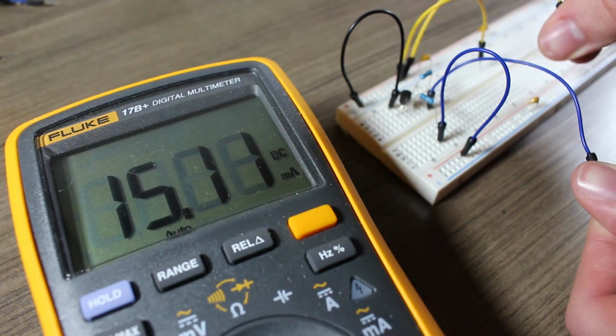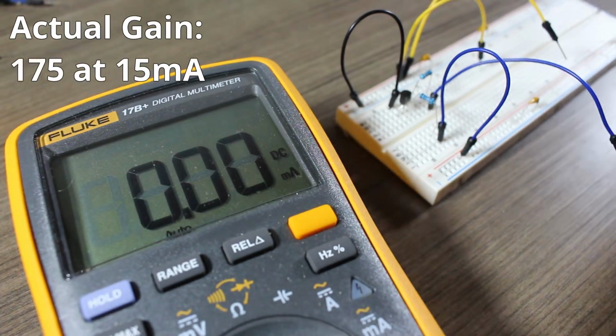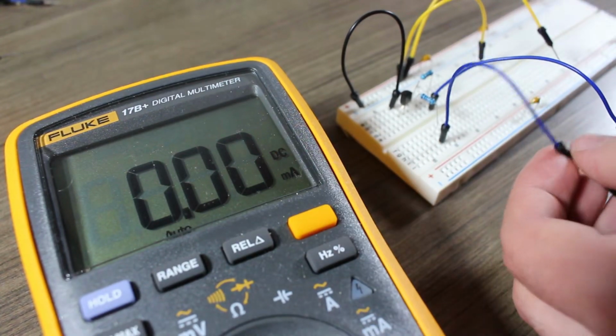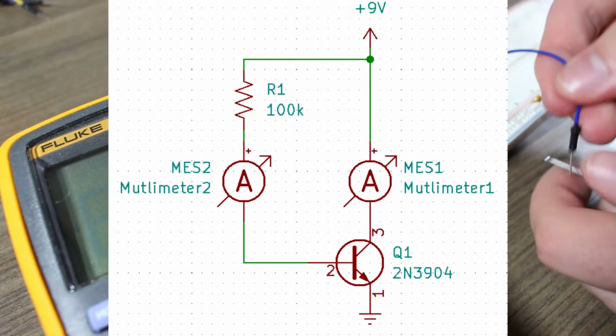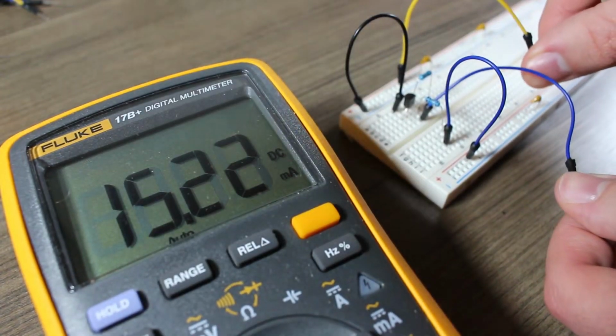If we solve for beta, we can see that this particular transistor has a gain of 175 at a collector current of 15 milliamps. This value is within the datasheet's range, so the math checks out. And for further proof that this transistor acts like a current source, I'll remove the resistor and connect the pins directly to the supply rails, and we will still measure that same 15 milliamps of current, despite changing the load.